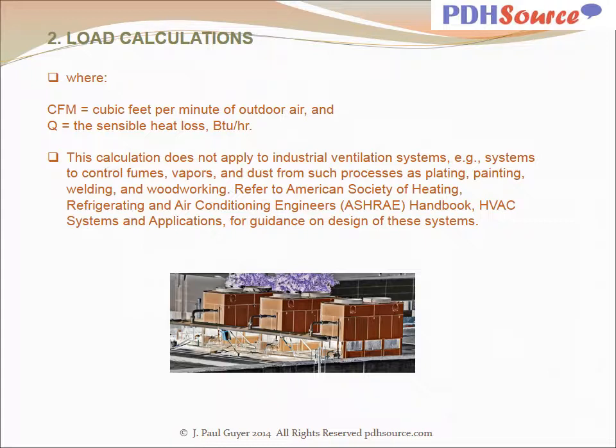If you have an industrial ventilation environment like that, then the air that you withdraw from the interior of the building is going to have to be replaced by an equal quantity of outside air, and that outside air that you bring in during the heating season is going to be cold and is going to have to be heated up, and that increases the heating load on your HVAC system.